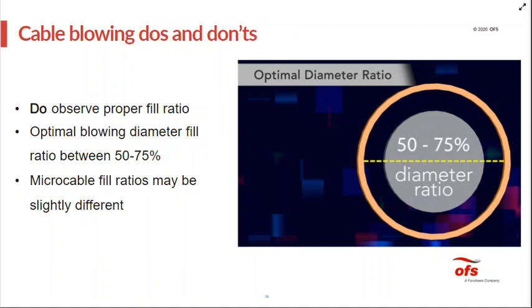Just want to note that sometimes micro cables, they'll push that limit a little bit higher. The micro cables being smaller diameter, smaller weight, doesn't take quite the same airflow to install the cable. So you can get by with a little smaller clearance between the cable and the interduct. So you may see slightly higher recommendations for micro cable applications.